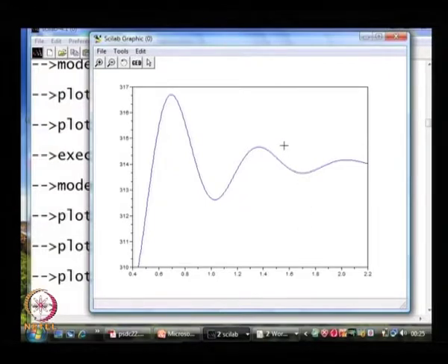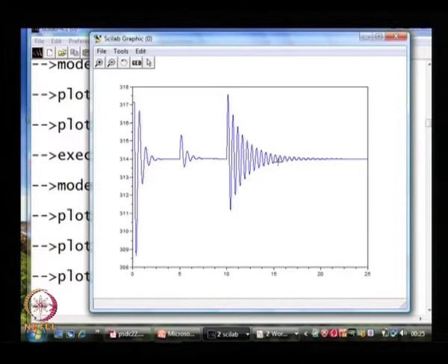So, with T m is equal to 0, the frequency is slightly lesser, in fact, the period is larger, and with larger values of T m with of course, a simultaneous increase of E f d, we see that the frequency in fact slightly increases. In fact, it is higher here compared to here. So, as the operating point changes, we get a change in frequency.